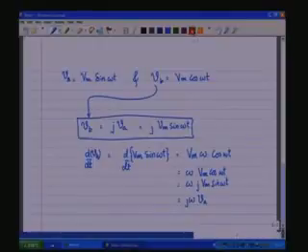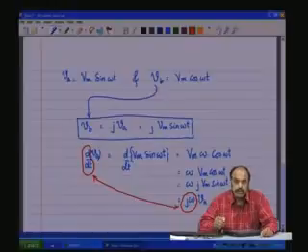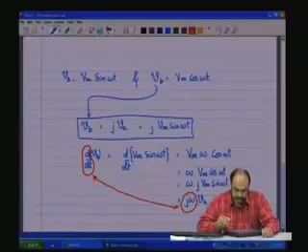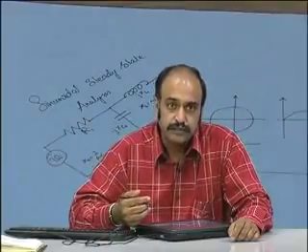So, what does it mean? That wherever you have d by dt, you are going to get this term. So, we can have a mechanism where we replace d by dt's with j omega to obtain the sinusoidal steady state equations. So, in the state equation, wherever there is d by dt, replace it with j omega. That will give you the sinusoidal steady state equations. We will see that shortly.